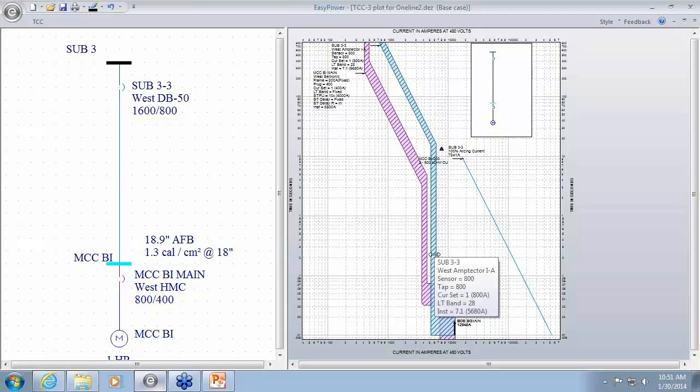Where in this case, by reducing that setting, you reduce the incident energy much more. So this may be one case where you do it, where the other one isn't, just because reducing your incident energy from a really, really high number to something that's very low may be a trade-off that you're willing to do.